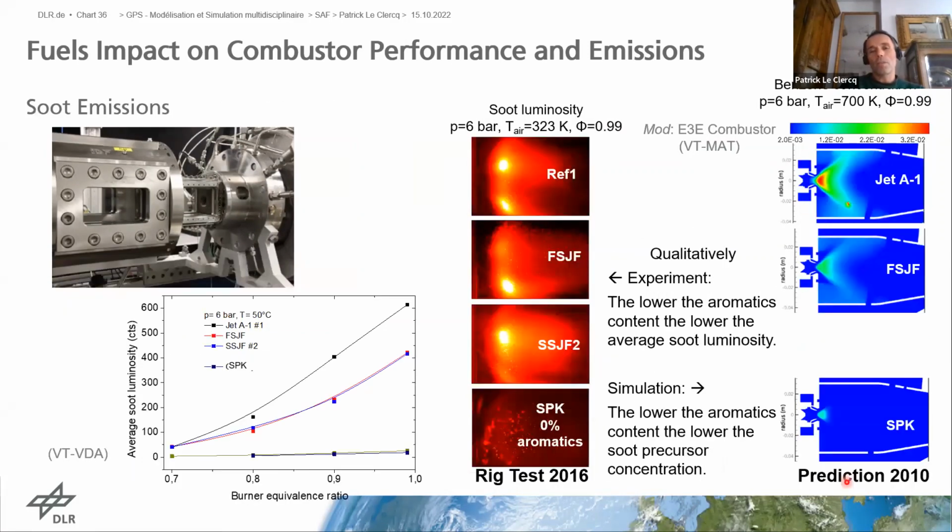However, now if you look at the soot formation, here it's the soot really from a visual viewpoint. Soot is basically this red orange, even in a candle flame. The orange part of the candle is actually the radiation coming from the soot. And if it was blue, like your gas burner when you cook, it's from natural gas. There is almost no soot.